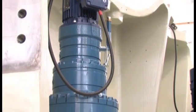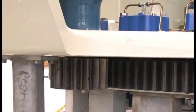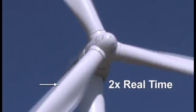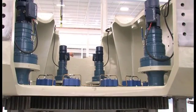Actuators are devices such as electric motors or hydraulic cylinders that create motion and can be controlled with an electrical signal. The controller turns them on in order to bring the system back to the set point, and then it shuts them off until the next error occurs. Let's look more closely at the yaw control system.